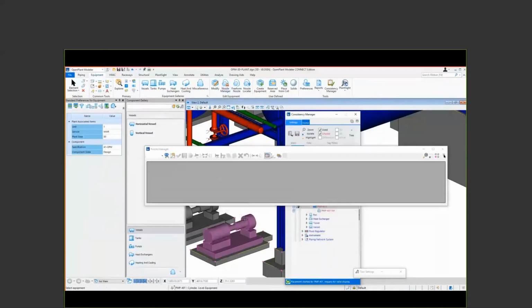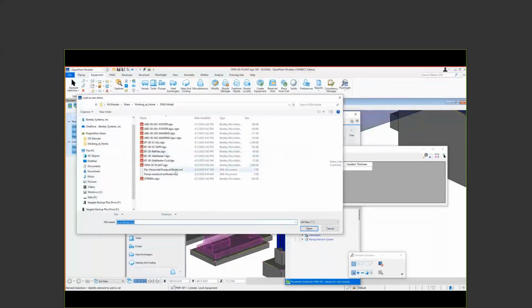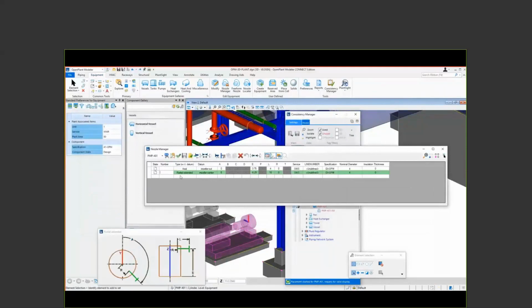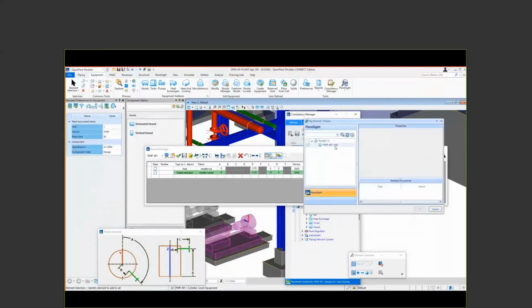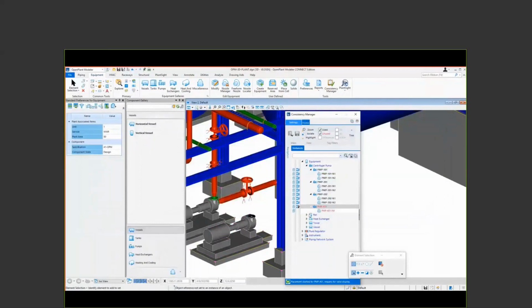Next, we're going to insert the nozzle. So again, I can have predefined templates to insert nozzles at different locations and dimensional properties. But I can also browse out to PlantSight, so PlantSight knows that I'm on PMP 401 and it knows there's this unused nozzle out there from the PID, and I can insert that from 2D to 3D. And you'll see these icons that show if it's been placed in 3D versus 2D.